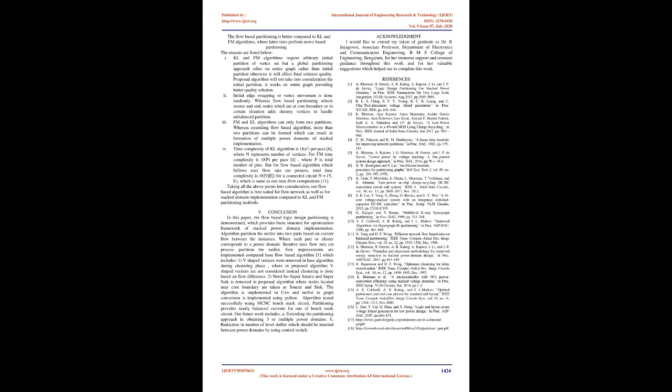But for the flow-based algorithm, which follows the max flow min cut process, the total time complexity is O(VE), for a connected circuit n equals V, E, which is the same as one max flow computation. Taking all the above points into consideration, our flow-based algorithm is best suited for the flow network as well as for stacked domain implementation compared to KL and FM partitioning methods.